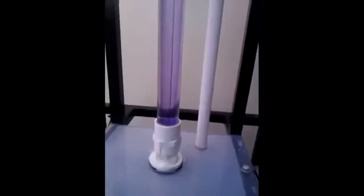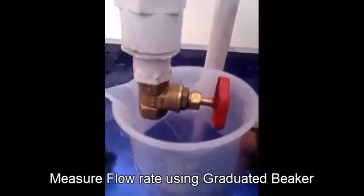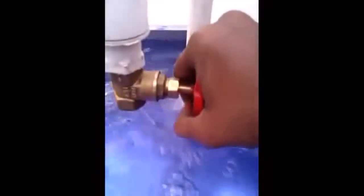If you maintain this low velocity, it means the laminar length is bigger than the pipe length. So along the whole length of the pipe, you can experience laminar flow. Now if you increase the velocity, you will experience the transition flow. Transition flow is in between, like it's not mixing and mixing. You will have vorticity or turbulence, but still you can distinguish, right? So this one is a transition flow.